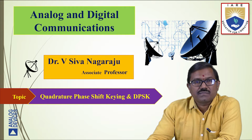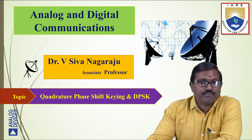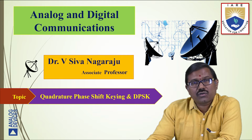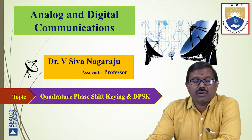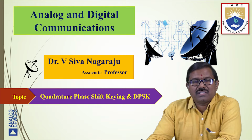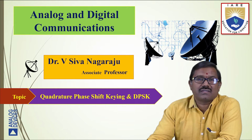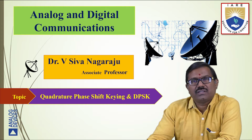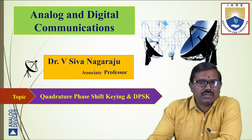You can use phase information or not. With phase information, we call it coherent. If we are not using any phase value for retrieving the message signal, that is called the non-coherent version. I am saying all this because DPSK, differential phase shift keying, can be viewed as a non-coherent version of PSK. So that is a little introduction to coherent and non-coherent.